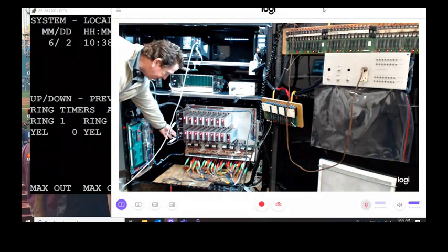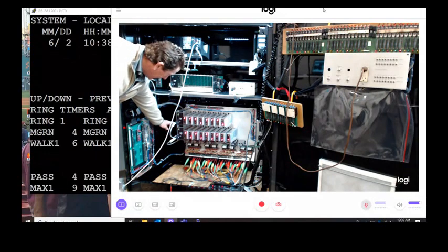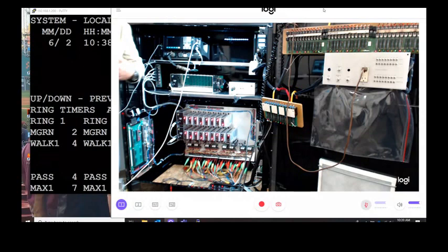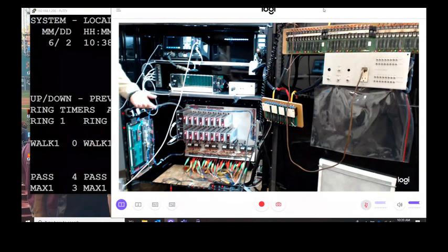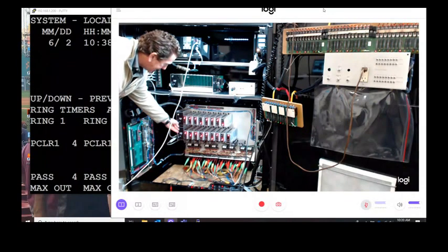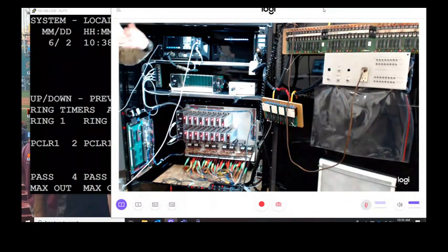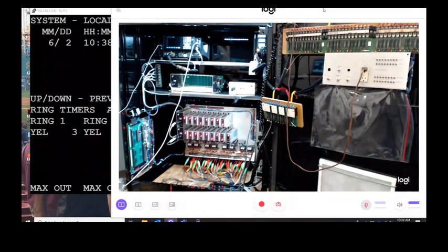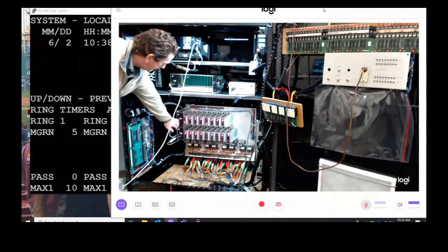Our BIU number 2 is our lower BIU. Each of them, when they fail, gives you a specific frame fault, 138, 139, 143. So as I'm turning on the BIUs, it's going to give me a specific frame fault that's addressed to either one of these.